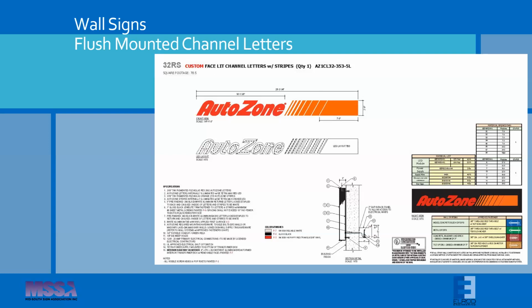For example, if the wall is EIFS with styrofoam board, one of the things you want to make sure you don't use is anything with urethane adhesive in it or sealant, to avoid melting that styrofoam. And if the wall is brick, it's important to know that you can only install one anchor per brick. So the anchor spacing of a sign, particularly when you look at this example with these slashes for the AutoZone, they're pretty small, and at least in the center of the sign, they're fairly tightly spaced together. You can only install one anchor per brick. So that anchor spacing is important.